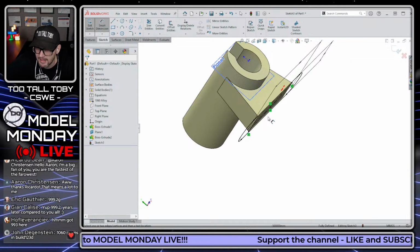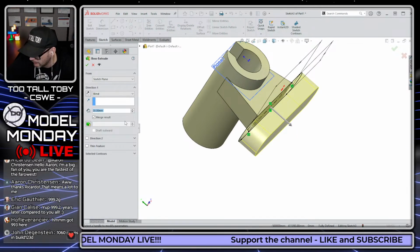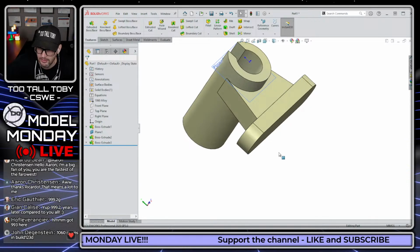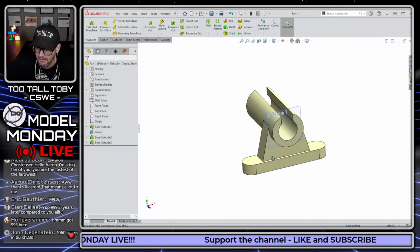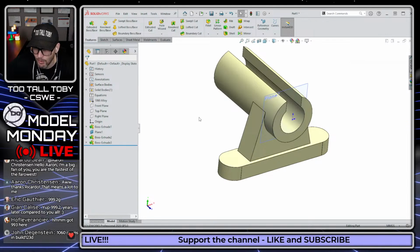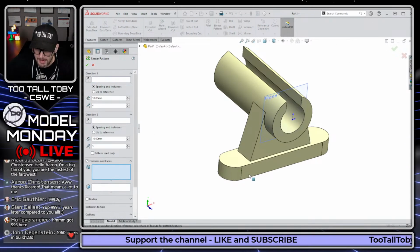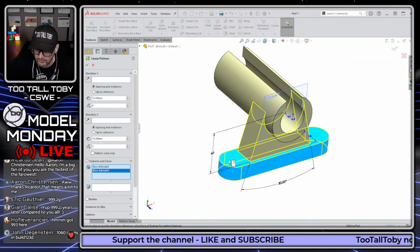So now we're ready to take that geometry and extrude it, and that's going to get extruded to a depth of 20 millimeters. And there we go. That's our first leg. Now, this is where it gets really cool. For our second leg, what we could do is choose this option for linear pattern. So with linear pattern, we could say that we want to pattern this leg and this foot.